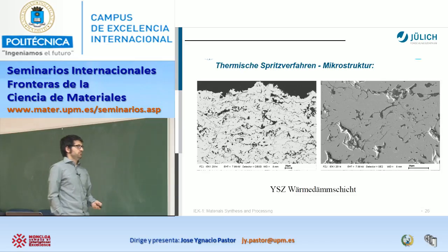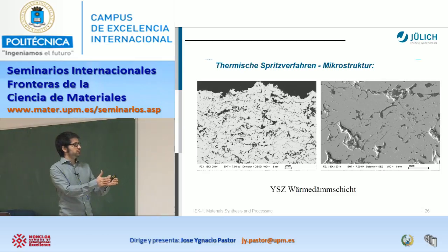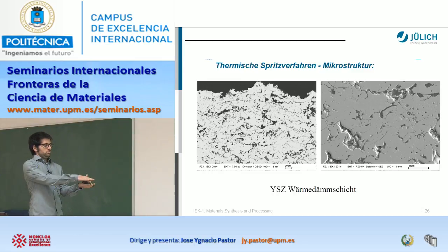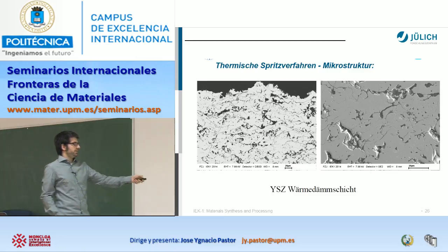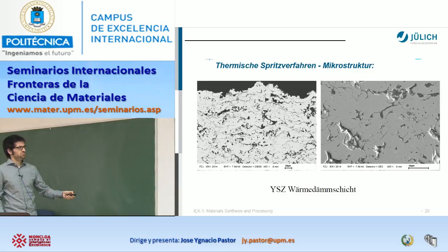And here, finally, is the cross section. You apply your powder with the gun, and then we cut it and analyze the cross section and the microstructure. And it's what I told you at the beginning.